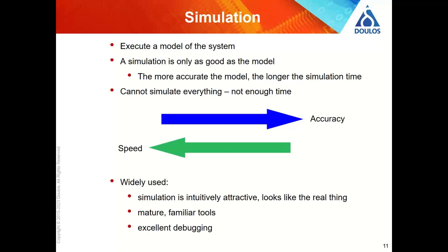Now, if you're writing RTL code, then that RTL code is going to be synthesized. The RTL code already contains descriptions of where all the registers are going to be, what happens on each clock edge. So that's a pretty good model. It's pretty accurate in terms of if your VHDL or Verilog model does something on a particular clock edge, then you can be sure the hardware will do so as well. Okay, but it depends how much accuracy you really need. And the problem's always been, when you're writing a simulation model, the more accurate it is, the longer it takes.